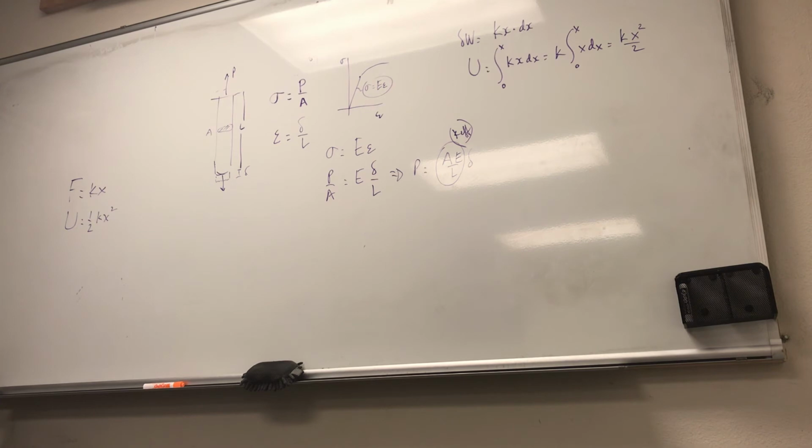There's one key thing about dampers to find what equivalent damping is. For a spring, the force is proportional to the displacement. For a damper, the force is proportional to the velocity. That's the key. So you need to rewrite the stuff so that force is equal to some thing times the velocity. That big thing is going to be the equivalent C. We'll talk more about this.